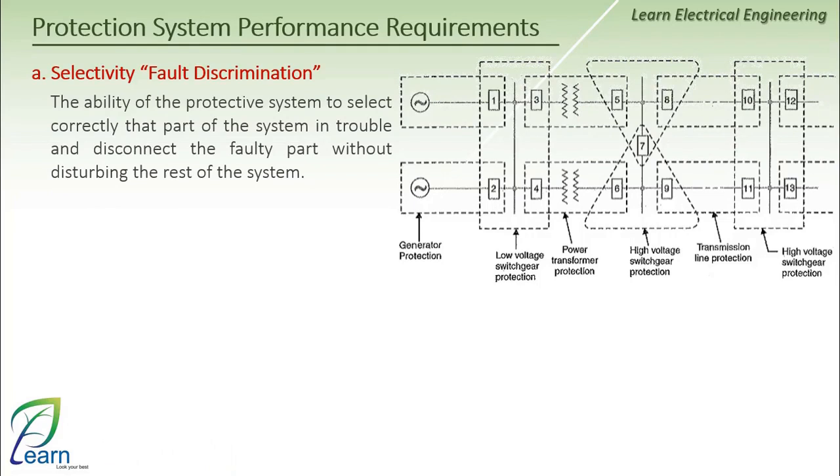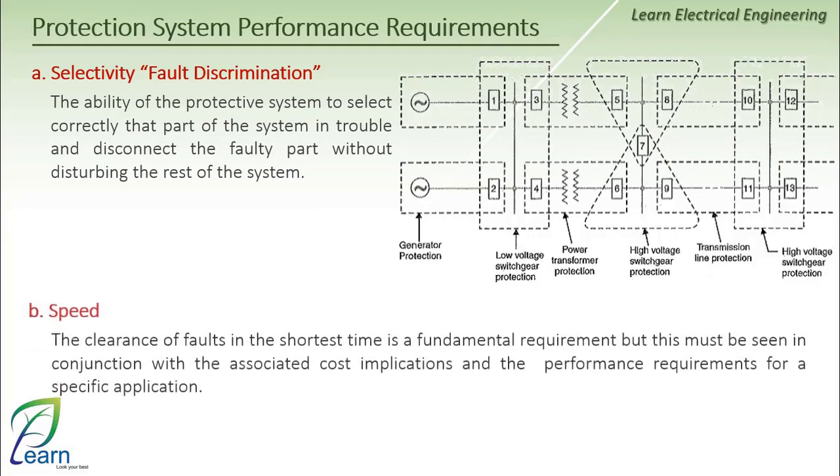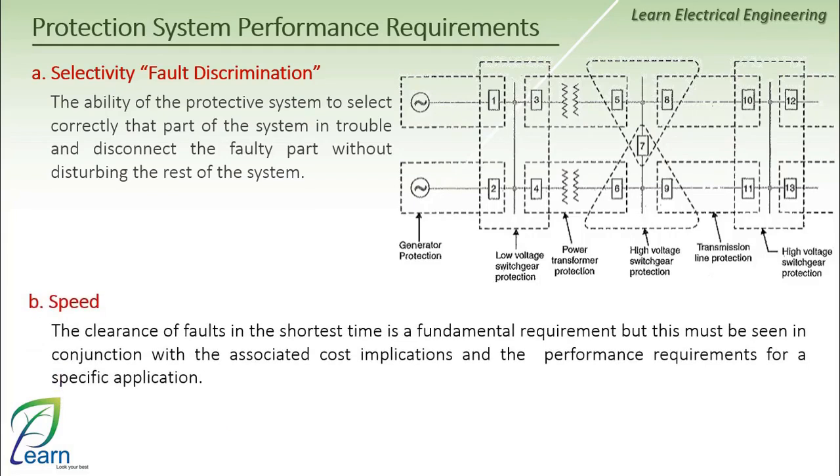If a fault occurs in one of them, there is a set of related protection devices that use the trip command to isolate only the logical zone within their area. Secondly, there is the speed, which refers to the speed of fault isolation. In the event of a fault occurrence, the faulty zone must be isolated at the specified time according to the protection function setting.